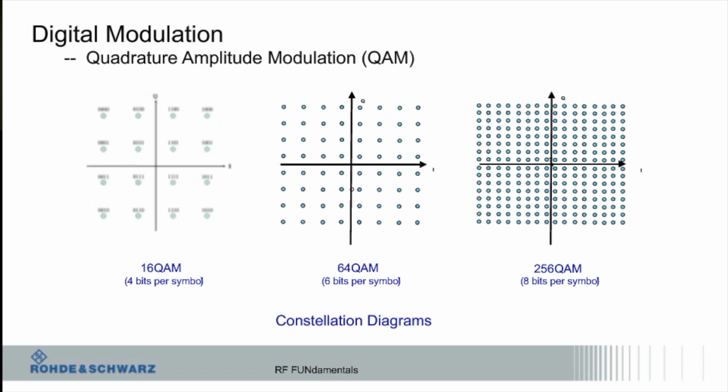What's the diagram showing? This is if I'm looking at a BPSK signal, so it's modulated on the carrier, ready to go. I'm looking at what is the bandwidth of that signal. Now I'm looking at a similar carrier. It's actually the same carrier, but instead of having BPSK, it has 8PSK. So it's a different type of modulation that has more bits per symbol, right? This has 1 bit per symbol as opposed to 3, but yet they still use the same amount of bandwidth. That's really the key takeaway there.